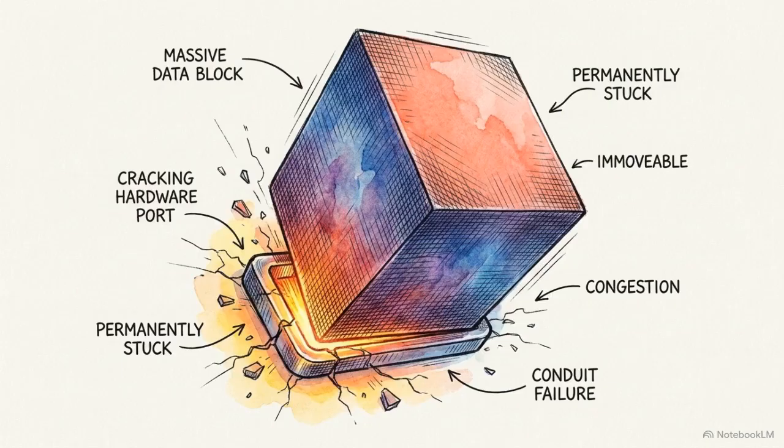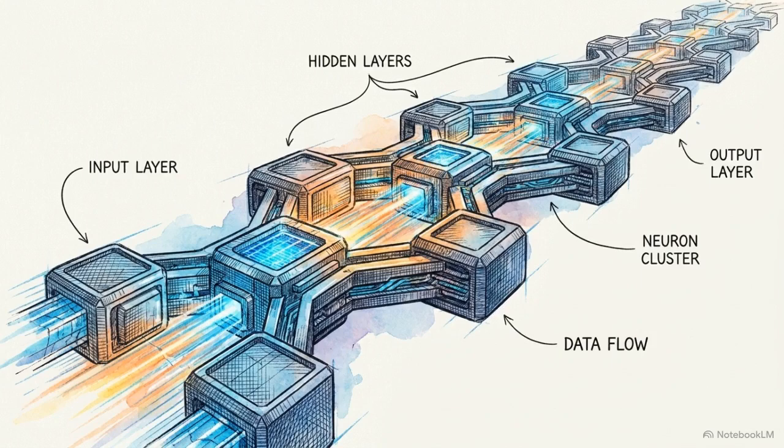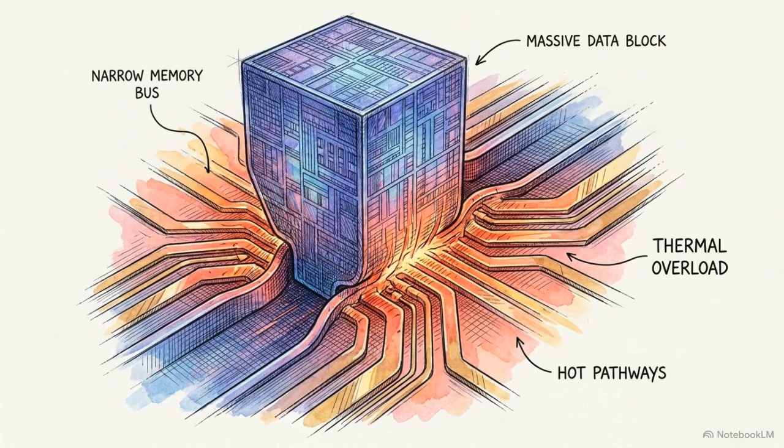Tiling takes a problem that scales quadratically across a slow memory bus and converts it into isolated, localized mathematics that safely respect the strict physical limits of the SRAM. This I/O awareness also solves the critical memory bottleneck during the backward pass of model training. To calculate gradients, standard training requires the hardware to save the massive n times n intermediate matrix from the forward pass. When it's time to apply the updates, standard architectures execute a slow, heavy read operation, pulling that saved matrix out of the HBM.